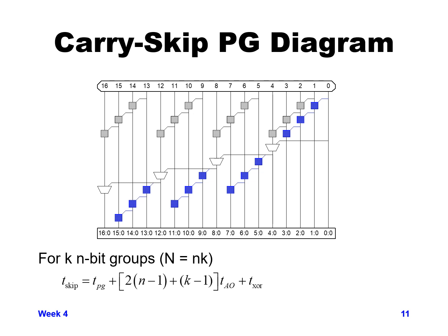and the total number of AND OR functions that we go through are basically the ones related to each bit of each group of 4. We have 3 at the beginning and 3 at the end, so that's n minus 1 times 2 AND ORs that we're going through for the gray boxes in the upper right and the blue boxes in the lower left.